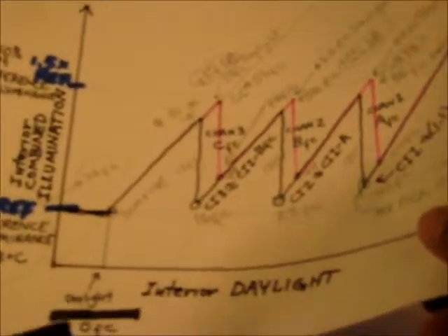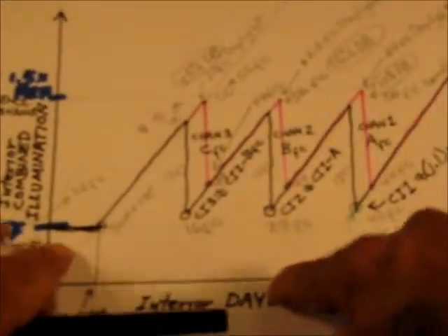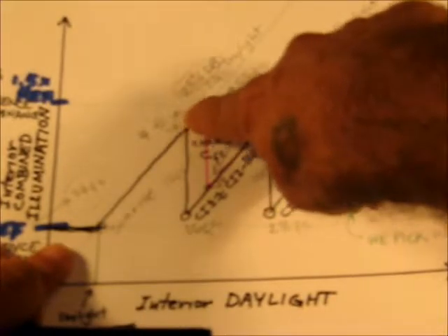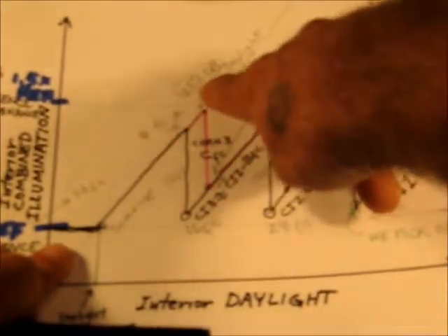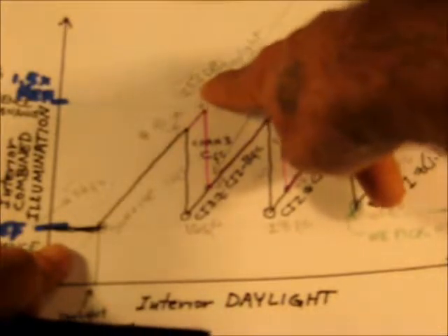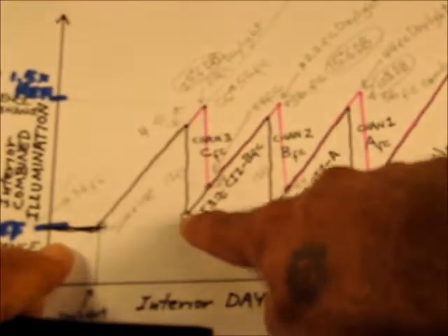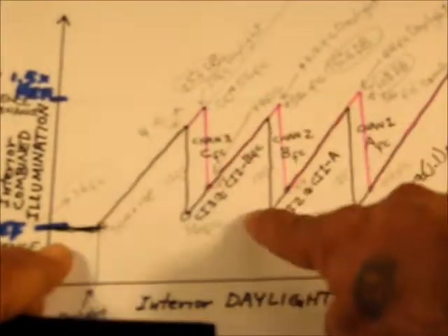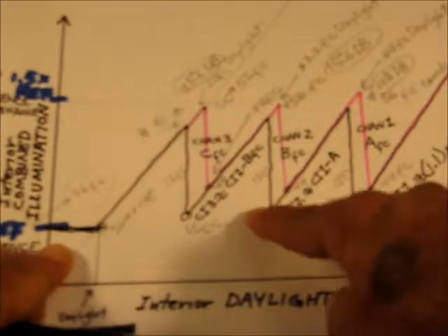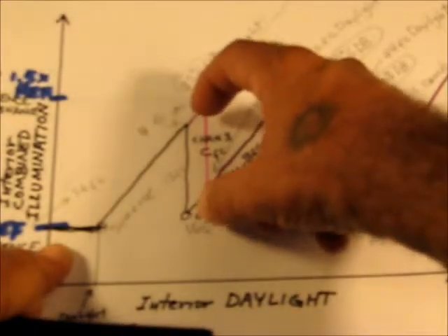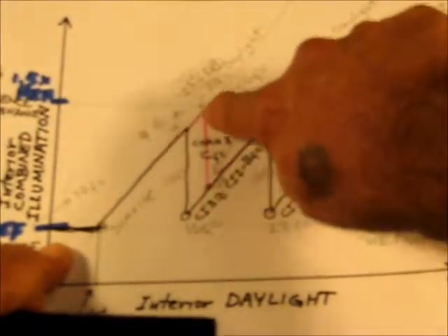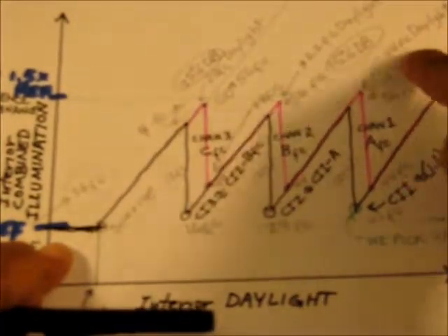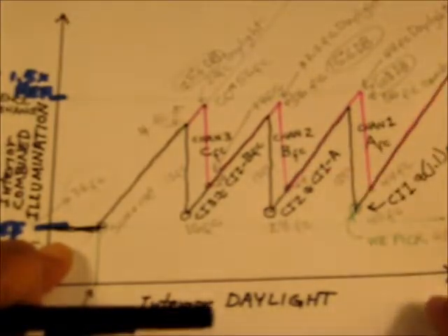In this controller, if you will recall, we first need to determine what our deadband is in actual foot candles, and then determine a deadband percentage setting, which is based on this cut-in value when a stage of lights first turns on. Now, we know that our cut-out value will be higher by at least 10% because that's the minimum we can set in this particular controller.